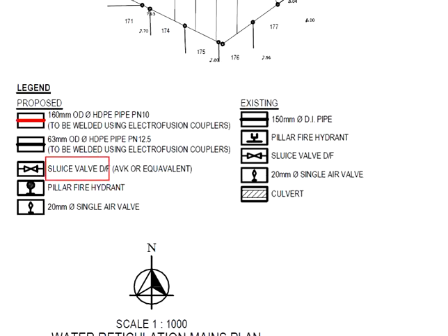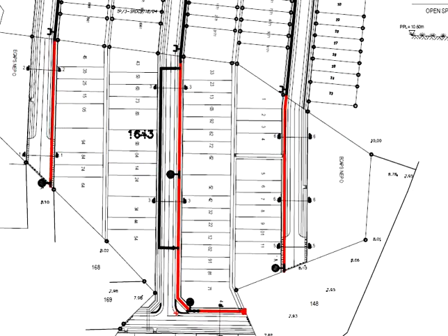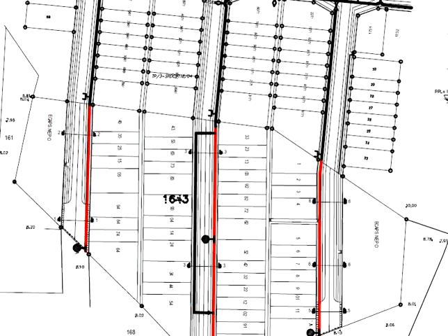We have the switch valve which is placed at the junctions or the potential junctions. You never know. In future, this development area may need to tap the water here. Therefore, in this case, probably you will need a switch valve in the junction here. You may also require the switch valve here, or probably here and here.